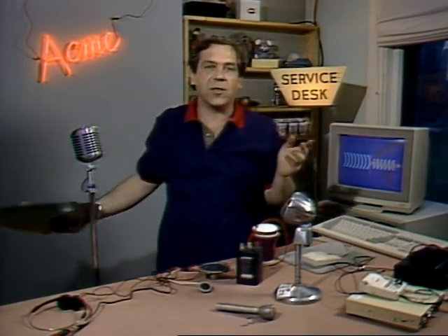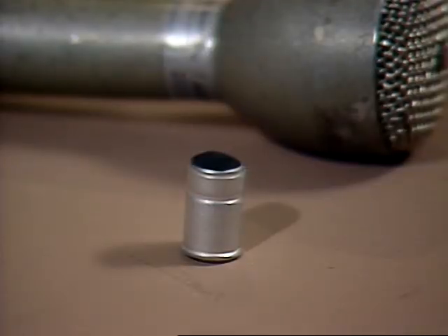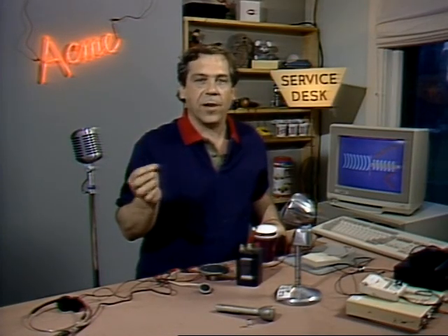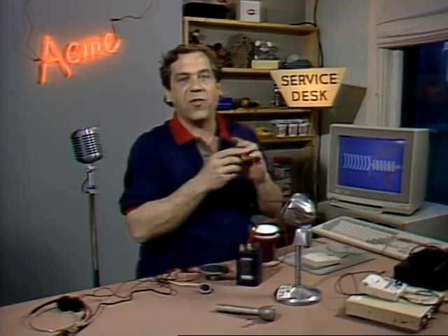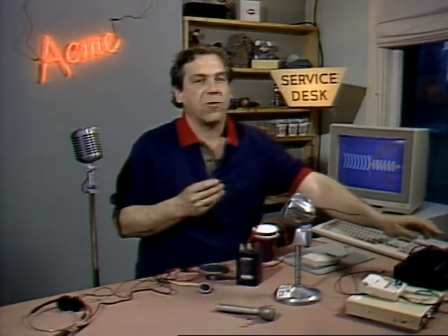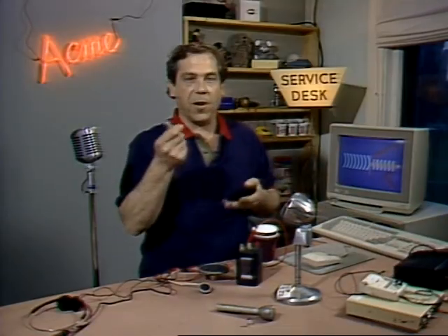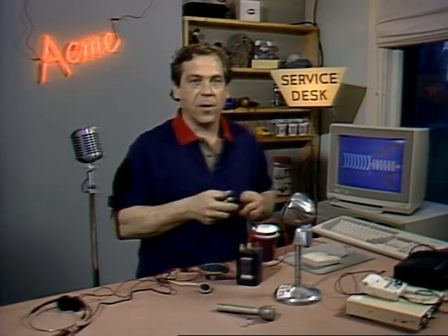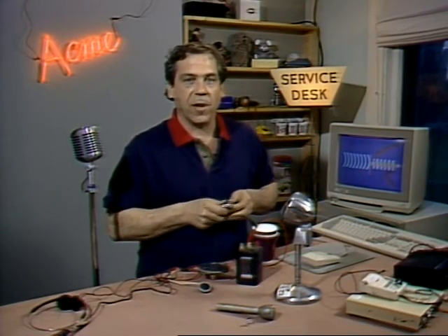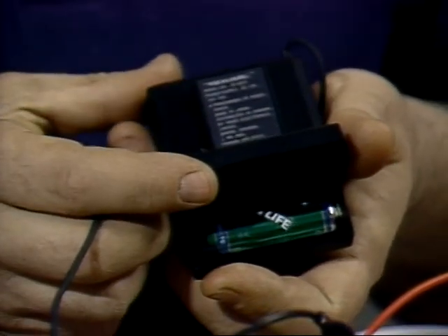The electric condenser uses a permanently polarized capacitor. There's no power supply. But by a kind of a curious irony, the signal's so weak that it can't even make it through 6 feet of wire. So all electric condenser mics have an amplifier right inside the microphone capsule. The amplifier does require a power supply, but a simple 1.5-volt cell is enough.